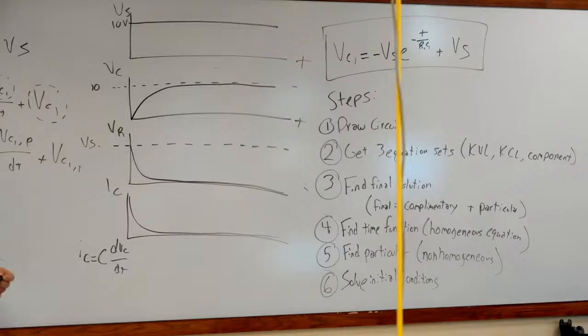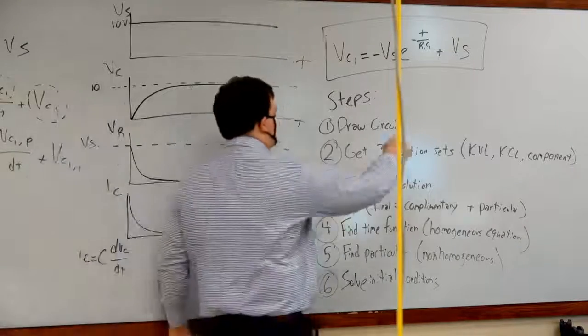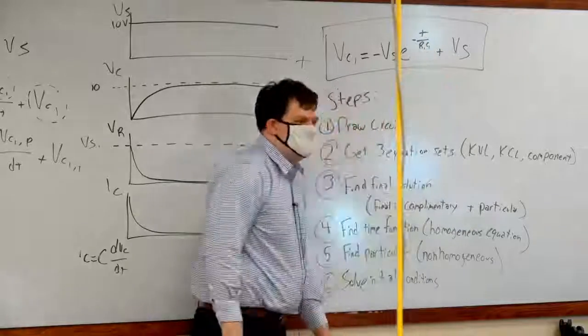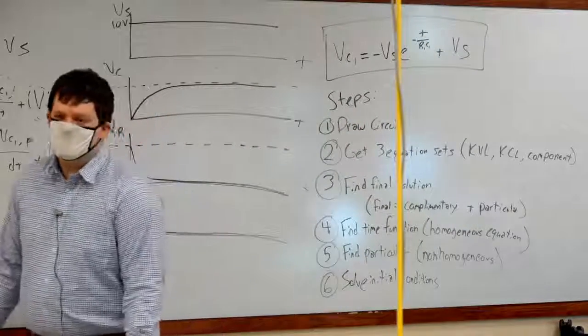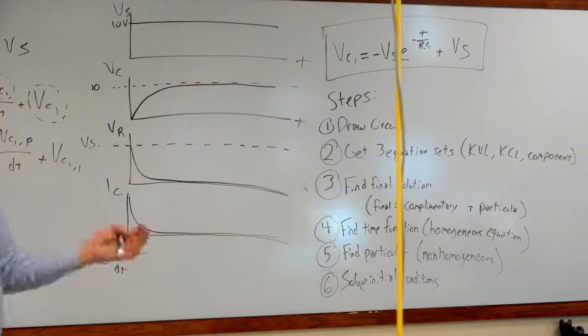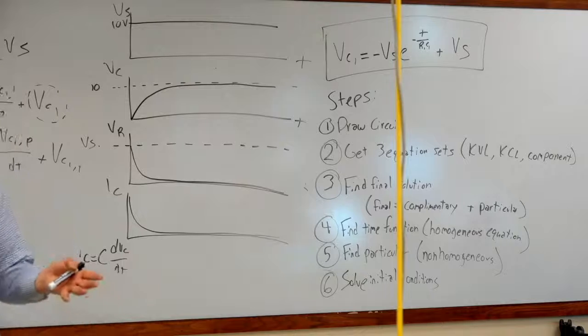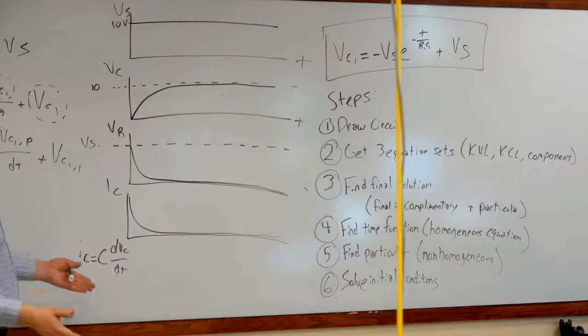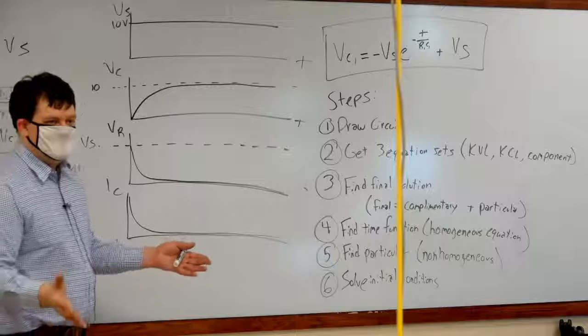What that means here is in order to make this value smaller, R1 and C1 have to be larger values. If you have a higher capacitance, it means you have more charges that can be stored on the capacitor, okay? So having more charges being able to store it on the capacitor means it takes longer to fully charge the capacitor. That makes sense.